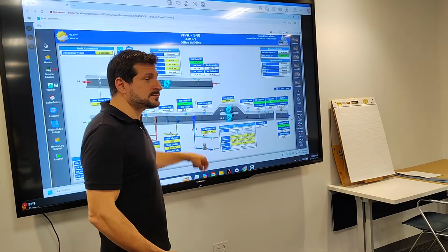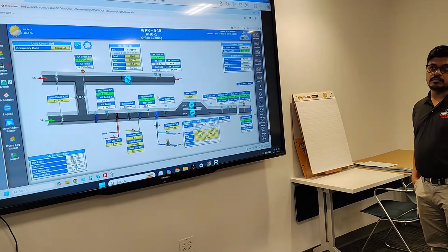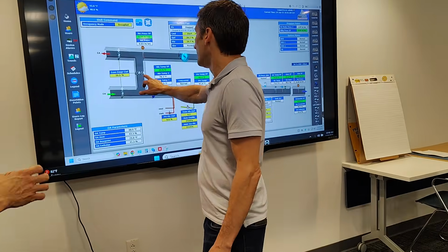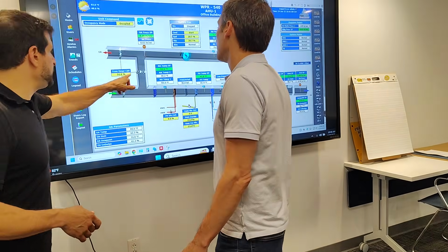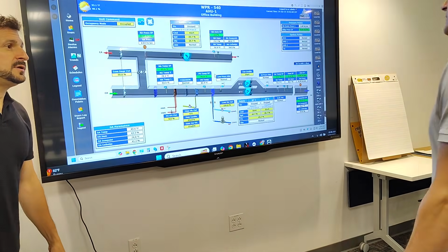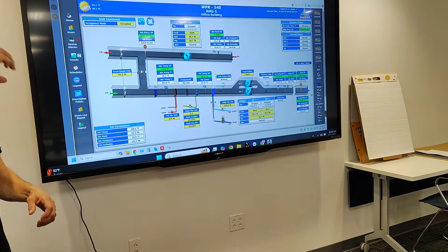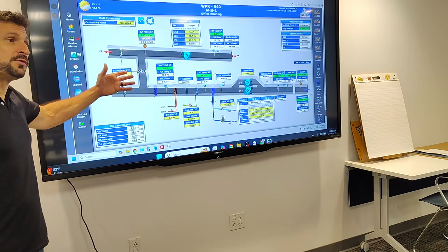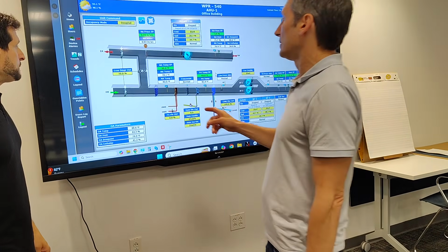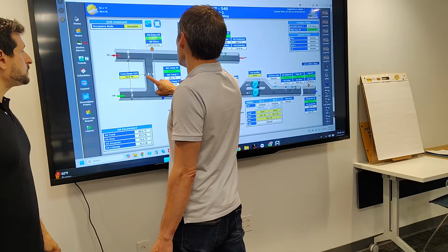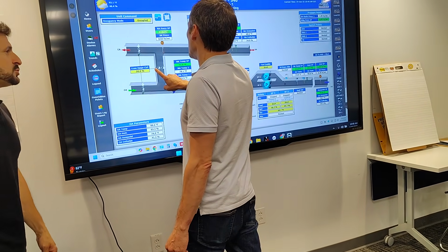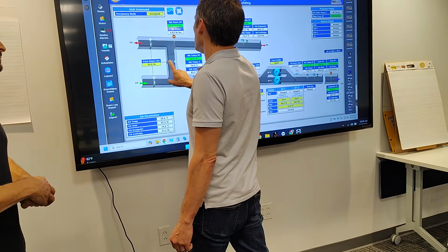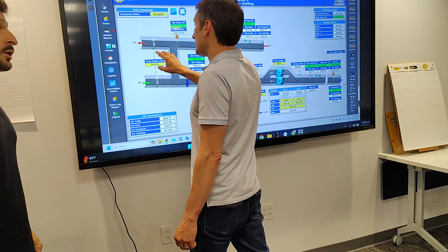Okay. Can I physically go look at the dampers? Sure. So you're saying this is 50%, and what's this? 50, 50, 50. They're all 50. Okay. You can override the damper here, but why is it equal? Because it's the same voltage signal from the controller to all three dampers. All three dampers are controlled by one output. Dan was able to control them individually. No, he wasn't.